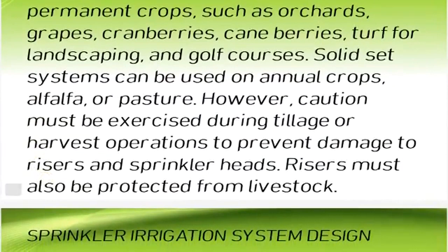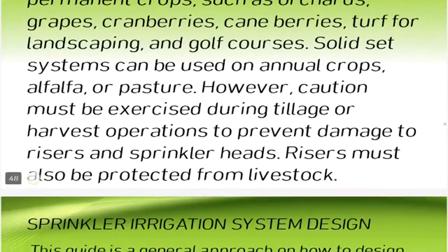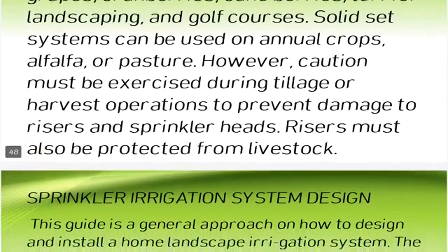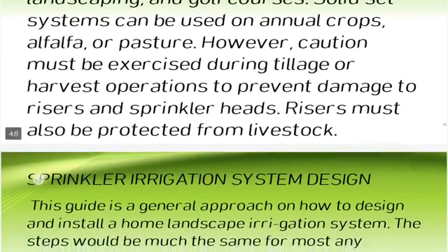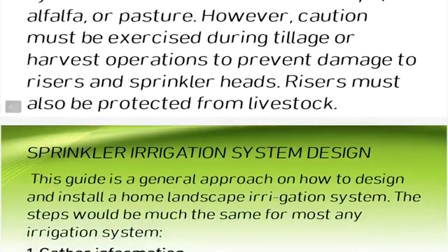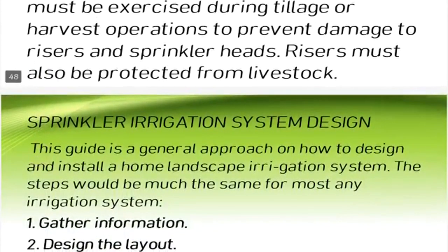Solid set systems can be used on annual crops, alfalfa, or pasture. However, caution must be exercised during tillage or harvest operations to prevent damage to risers and sprinkler heads. Risers must also be protected from livestock.